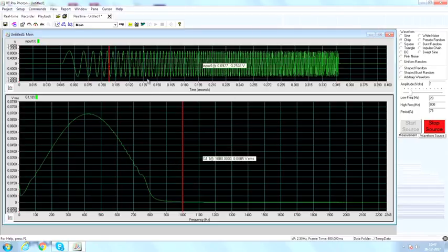So, this is a non-stationary signal and this is the FFT of it, assuming that it is a stationary signal, and this is not quite the right representation of such a signal, because this says, you know what, a frequency of 400 hertz of maybe 0.07 amplitude exists at all times. That is not true here. So, we need to do what is known as a time frequency analysis of such signals.